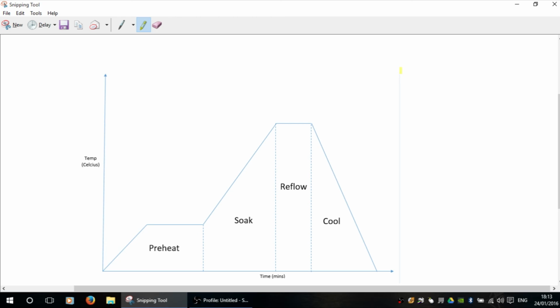Essentially, like I say, these things are hygroscopic. They encourage moisture from the air to draw into themselves, especially when they're sat around dormant. So if they've been in a box in the attic because they're knackered, or they've been shoved in a drawer for 6 months and not turned on, then that can all encourage moisture to absorb into the substrate of the BGA.